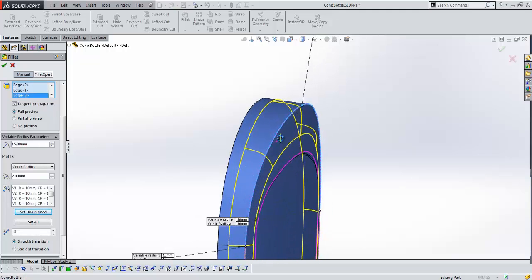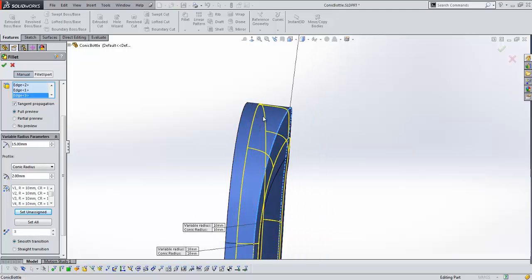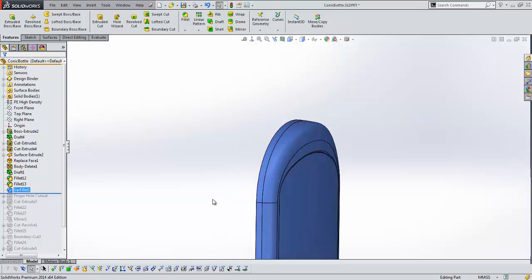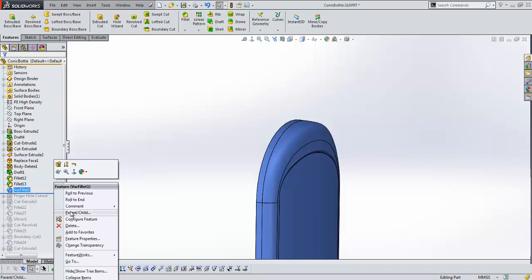By doing this, we can see that my fillet now peels back a little bit more, it's larger in size, and the shape is sharper. So starting from here, where this transitions out, its last point, we now start from a standard fillet and we move up to this sharper new shape. Once I accept this, we can see that we can have a much wider variety of shapes and we can get there significantly quicker with the new conic fillet tool. Let's see another area where this applies.